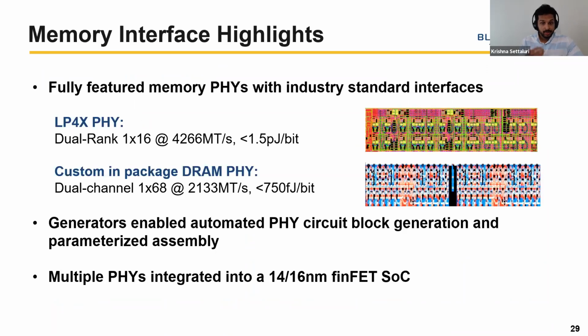And on the memory interface side, recently we had a very big milestone at Blue Cheetah where we actually have silicon proven results of our memory interfaces. In this particular case, generators were once again used to produce fully featured memory PHYs with industry standard interfaces. So this was an LPDDR4X PHY, as well as a custom in-package DRAM variant for one of our partners. Generators were used to assemble the PHY circuit blocks themselves, as well as parameterized assembly at a slightly higher level. These were taped out on advanced FinFET nodes, and as mentioned, over the past couple of months, our team has been working very, very hard to get the silicon proven.